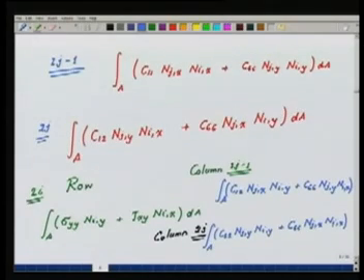Okay, so it's very easy to write these expressions, and what it is doing is this explicit operation of B transpose dB has been written in terms of the expanded expressions that you would have obtained. One can check that this is exactly what you will get out of the B transpose dB, and we can write it in a loop over the integration points and get the job done.